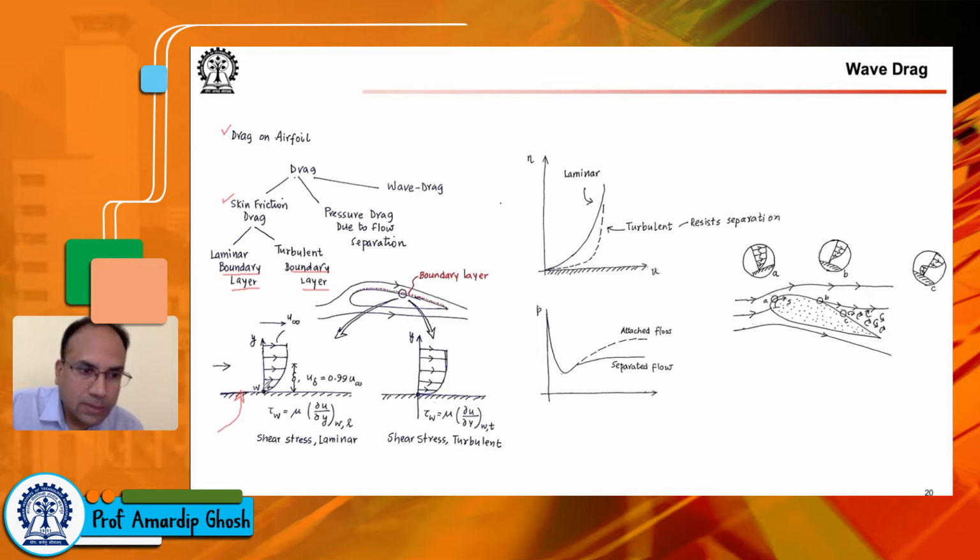The flow has a certain distribution. At the wall, the flow speed goes to 0 because of viscous effects. We have said that under some conditions of Knudsen number, there can be slip effects, but we will not look into those right now. For most of your applications, you can assume that the velocity of the flow at the wall for a viscous flow field becomes 0. So this is the relative velocity between the wall and the flow becomes 0.